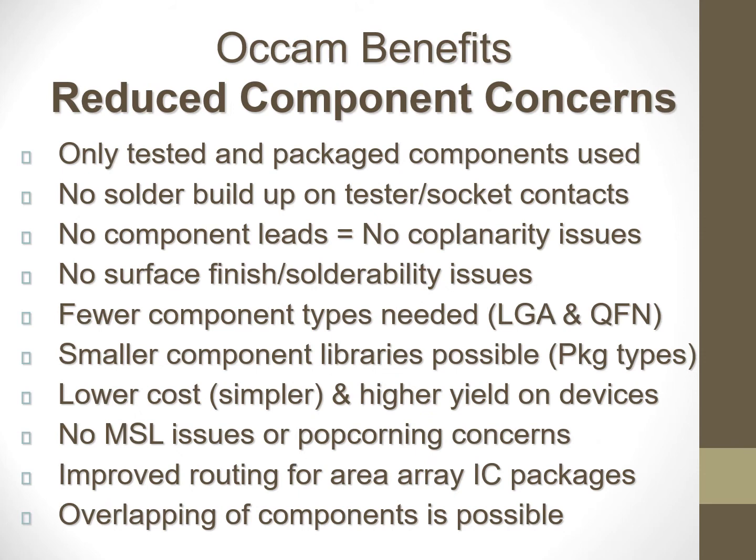There's reduced concerns about the components. Only tested and packaged components are going to be used. There's no solder buildup on the testers. You don't need to worry about coplanarity of leads. No surface finish concerns. We're looking at ultimately, and this will be explained in more detail, fewer types of components. LGAs and QFNs are the preferred ones. This allows you to get to a smaller component library in terms of packaging type, and you can get simpler, lower cost and higher yield on devices.